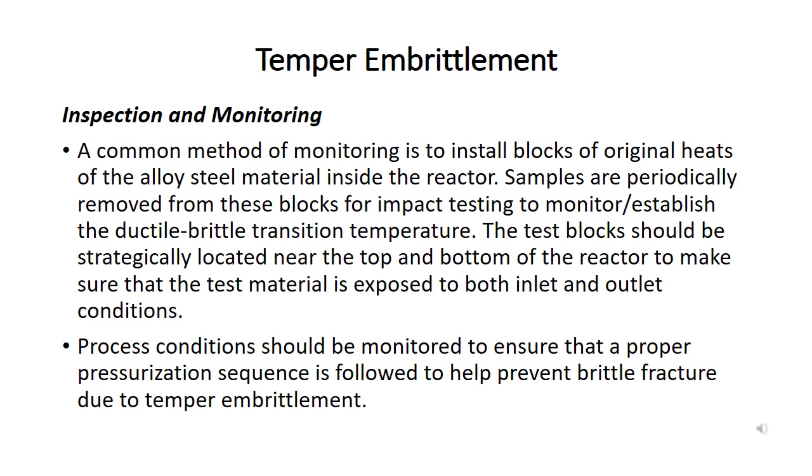Process conditions should be monitored to ensure that a proper pressurization sequence is followed to help prevent brittle fracture due to temper embrittlement.